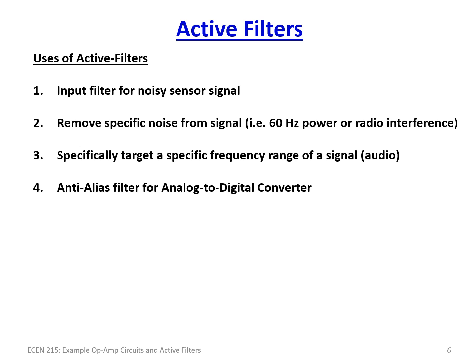There's something known as an anti-alias filter for your analog digital converter. That's just a fancy phrase for a low pass filter. If you use an analog digital converter, and we'll be talking about this in the microcontroller lecture a little bit as well, in the last 20 years embedded systems have become a forefront, and pretty much almost all signals nowadays are sampled by an analog digital converter so that you can do computations digitally upon the data you're receiving.